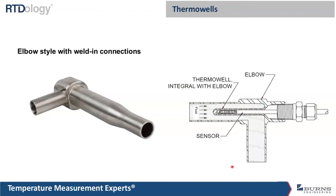Now these will have either a weld end like this that will be installed with an orbital welder, or hygienic ferrules can be attached here to make it removable if it's necessary for cleaning or replacement.